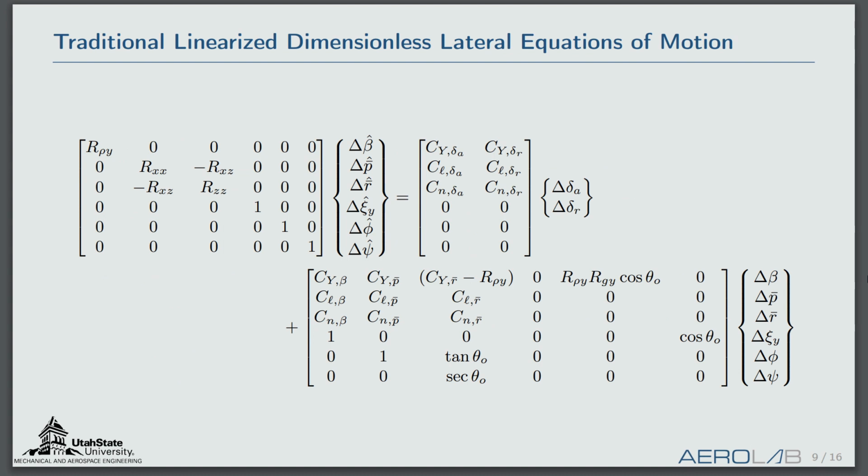You'll notice a lot of these c variables. Generally those are non-dimensionalized using dynamic pressure and wing area, and then usually there's a reference length somewhere in there. Now, those work great for aerodynamics, but what we wanted to look at was, they're not terribly appropriate for looking at the dynamics of some aircraft, where we're not so much concerned about the dynamic pressure, but we're more concerned about velocity, gravity, weight, and components of inertia.